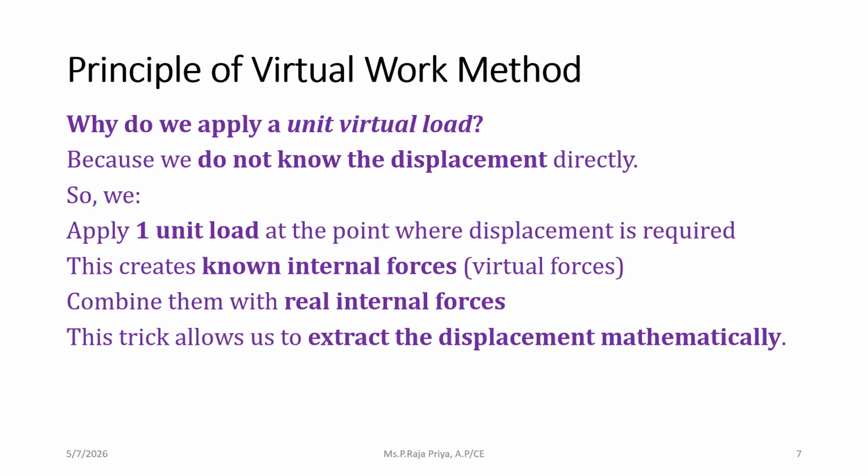And what do we do in the virtual work method? We do not know the displacement directly. To determine the displacement, we apply a unit virtual load, that is a 1 kilonewton load, at the point where we need the displacement.